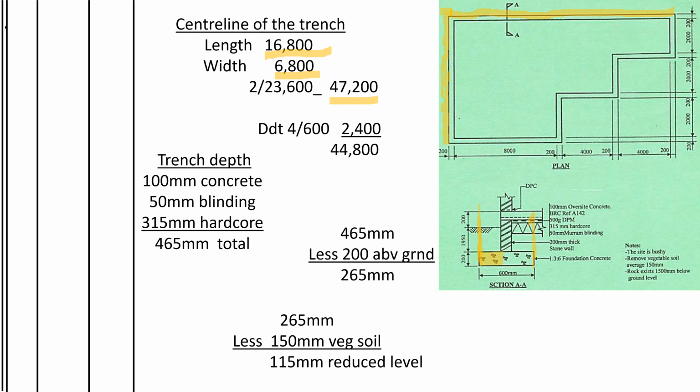Then we shall deduct, here it's where you note the difference, number of corners times the width of the trench. If you have not got that concept of center line, kindly go to the video on center lines. You need to understand this concept, because a lot of students get confused here. You have to take the external dimensions of the thickness that you want. Now our thickness here is the thickness of the trench, which is 600. So we shall take number of corners.